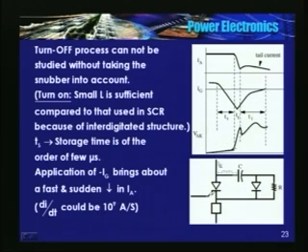Now because of this loop inductance and because of the turn on time of the diode, this anode current cannot start flowing through the snubber circuit immediately. And because of this, there is going to be a voltage spike, because of the inductance which is there in other parts of the circuit.